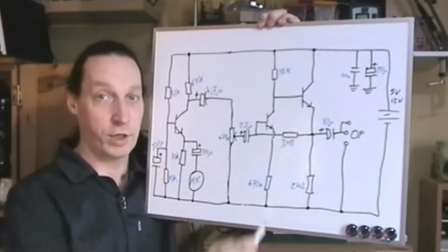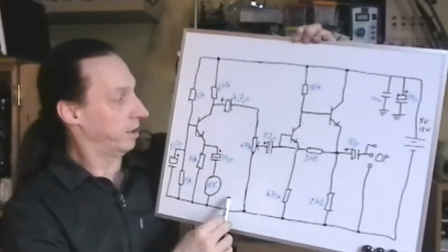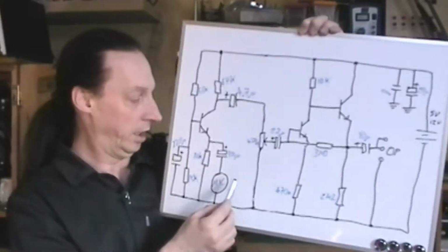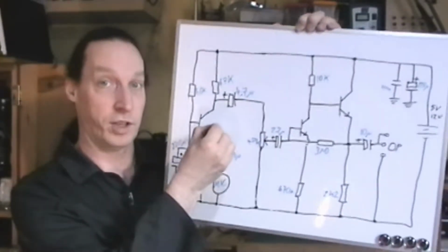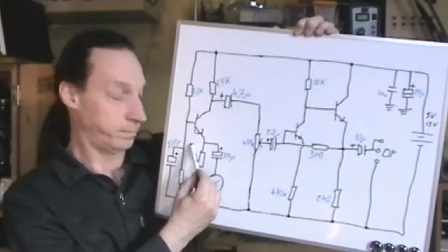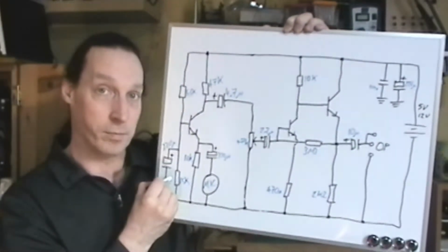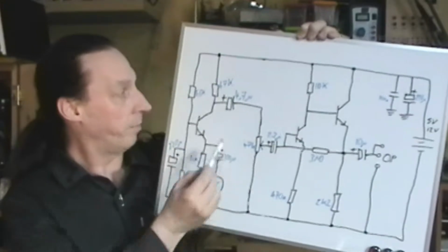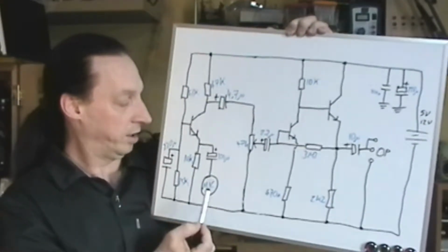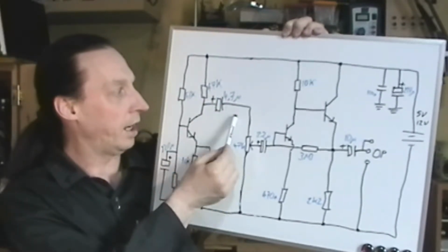As you can see, I've now redrawn this section in a slightly different format, just so I can see it in a way that I'm used to seeing it, which is a BC337 transistor, basically biased with a resistor divider, but we've also got a capacitor on that base as well, a collector resistor, a resistor on the emitter, and the output is on the collector there.